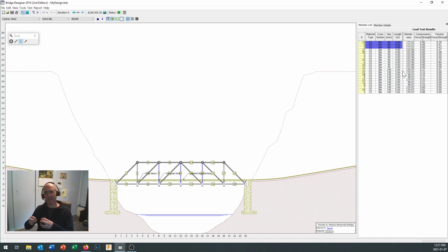simple because it doesn't matter how long they are, the strength stays the same. But let's do a sort by our compressive strengths in right here. And well, here we go. These members on the end tend to be our highest strength compression members because they get quite a bit of load. When you think about the forces that are coming in here, pick this node right here, okay?